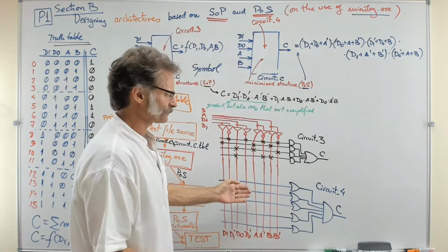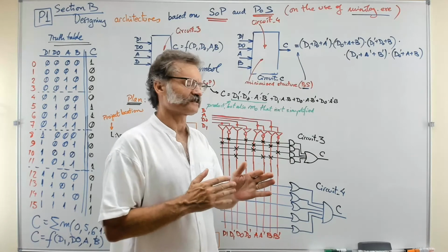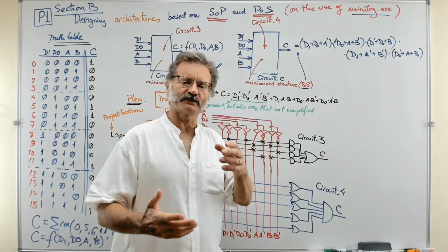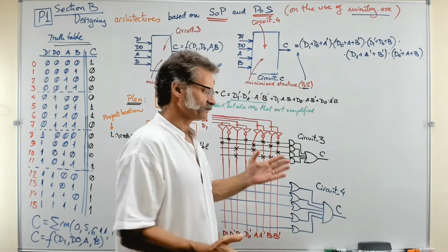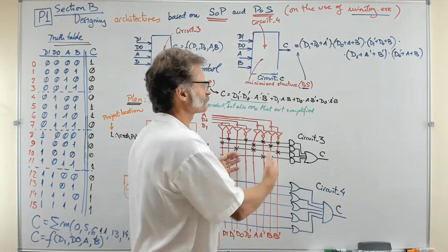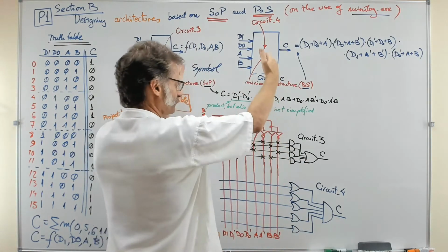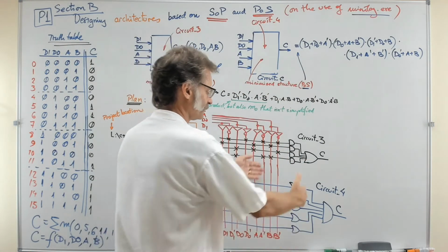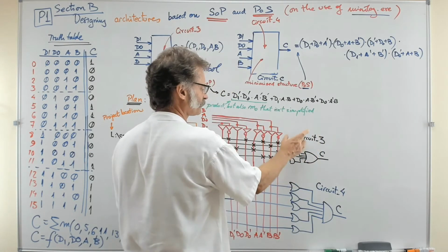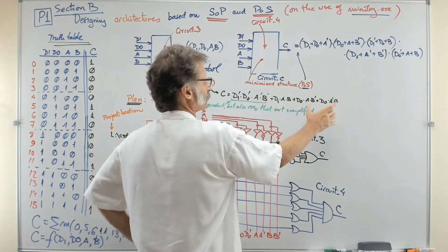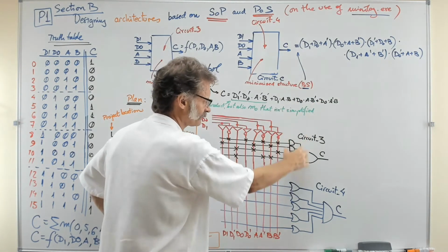You see, those circuits are quite regular with respect to the others that you can get using any kind of equation. Those ones, the canonical ones, and also the product of sums and sum of products, are very regular. They are that way, a column of literals. Then you have another level of gates, which is, for example, in this case, the products. Every one of the products can be placed in this second level of gates.